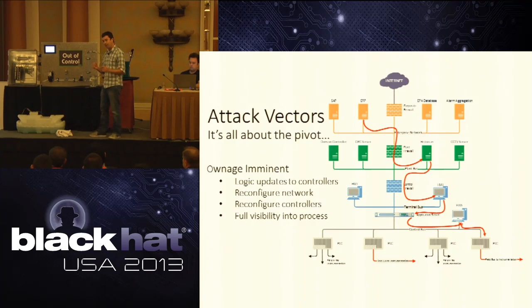still online. And why that's important is because in the olden days, you had to take a PLC offline, modify the logic, and then bring them back up. But you don't have to do that anymore. And the reason that you don't have to do that anymore is because plants require almost no downtime. You need your wellhead to be up all the time. So you're able to modify logic real time without ever bringing down the process, which is awesome for a hacker, right? Because nobody actually knows that any change has ever been made. The process keeps going on normally, or how you want it to go, but you never have to actually take it down.